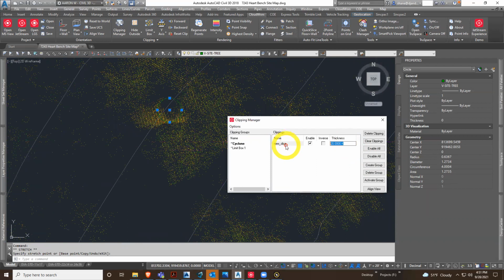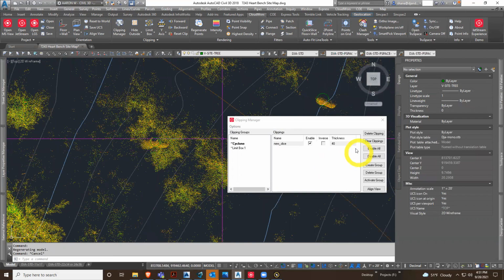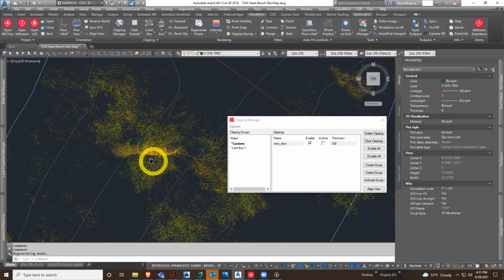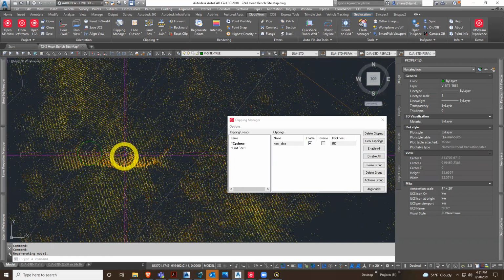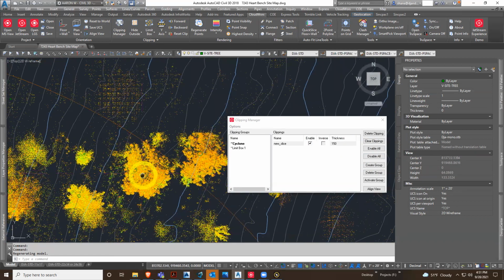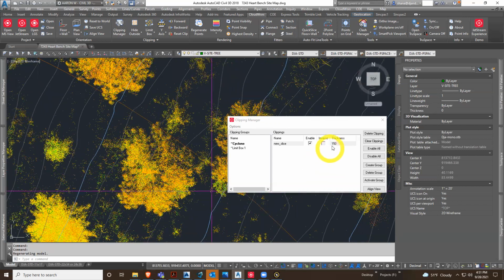And if I change my slice to twice the thickness in the Y direction, right? Because remember I established it by the Y, my slice, hit enter. Let's go to 100. It's thickening the slice. You can see the trunk increasing, right? So that helps me identify ground features like trees. Now I went up 150 and it's getting almost to the canopy of the tree.